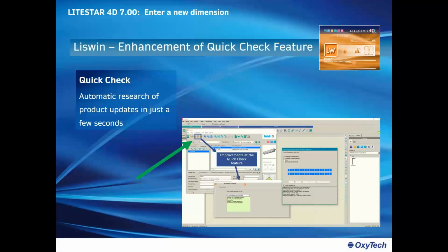Second point, you know that more and more the luminaires are driven through the current. So you can dim the light output using the driver. Finding a different current, you get a different flux. But how do we manage this information now? More and more the manufacturers are producing huge amounts of files. Why? Because per any current, they have to produce a single IES file, a single ULUM.dat file. And this is at the end a huge amount of files, but you cannot characterize the complete curve.